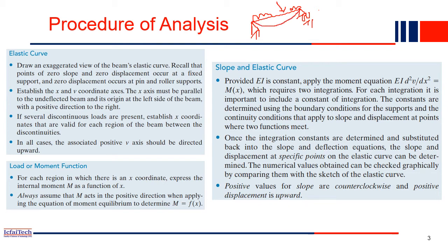This deflected curve, we call it the elastic curve. So our first job will be just looking into the supports and support conditions, and we have to draw the elastic curve. Obviously we have to draw it in an exaggerated manner, because in reality the deflection may not be that much. In reality maybe the deflection is very small, but for analysis purposes we will draw a very high deflection. That is our first step.